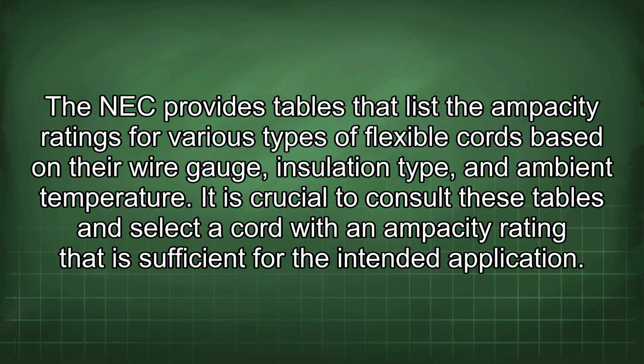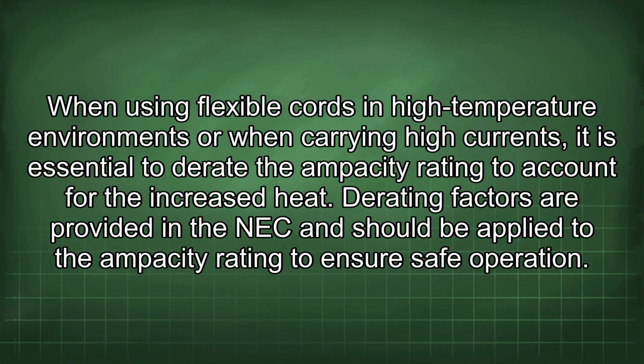It is crucial to consult these tables and select a cord with an ampacity rating that is sufficient for the intended application. When using flexible cords in high-temperature environments or when carrying high currents, it is essential to derate the ampacity rating to account for the increased heat.